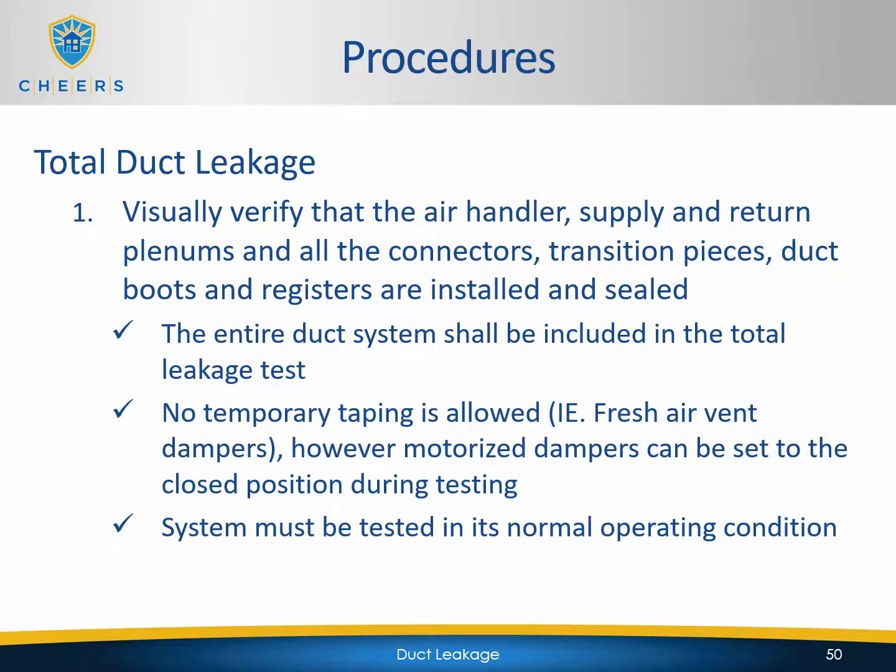So the first step is to visually verify that the air handler, supply and return plenums, all the connectors, transition pieces, duct boots, and registers are installed and sealed. The entire duct system shall be included in the total leakage test. You cannot portion off portions of the system, so it has to be tested as a whole.